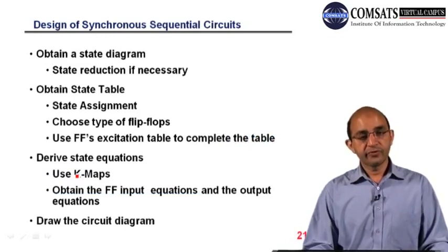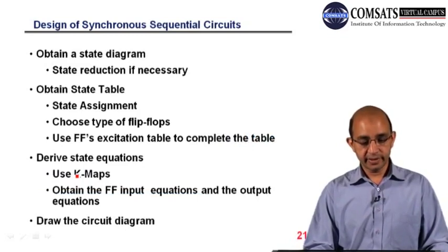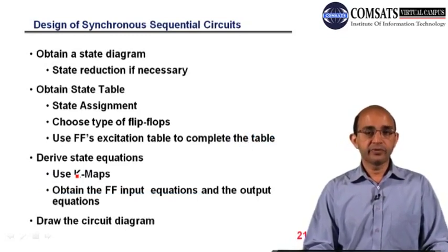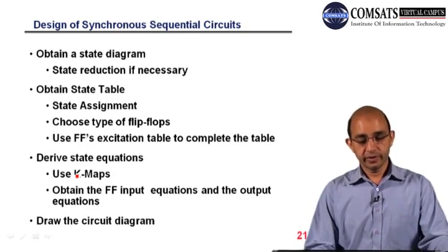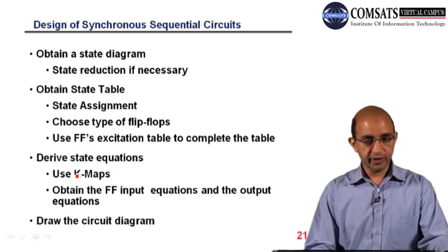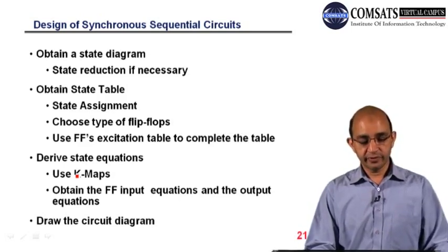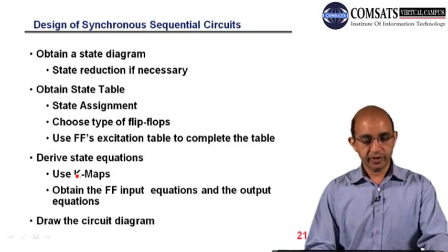And now we are moving from the analysis to the design. So we have to go through a certain number of steps in order to design sequential circuits. Just as whenever we perform analysis we follow certain steps, similarly whenever we design a sequential circuit we go through certain steps. So here we have the design of synchronous sequential circuits. First we have to find the state diagram. The next step is the minimization.